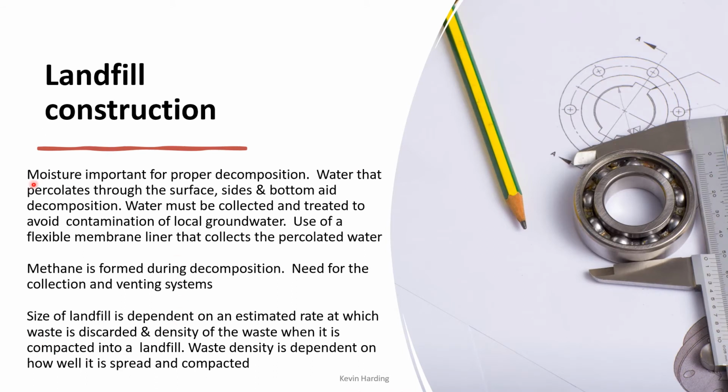So this all comes down to now, how do we actually construct this landfill? We've already mentioned this leachate, the water or the liquids that come through here, which is going to be critical in managing the environmental situation. That moisture content is very important for the proper decomposition, but we also don't want too much of it to leak into the ground. So let me just take a step back and go over this again. Moisture is important for the proper decomposition.